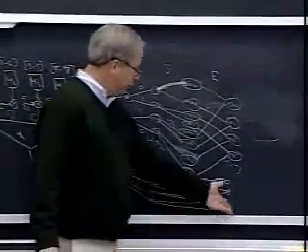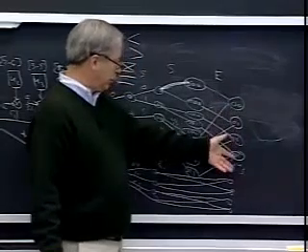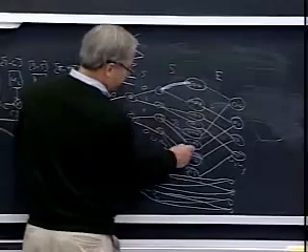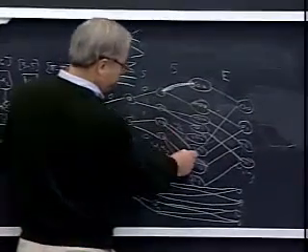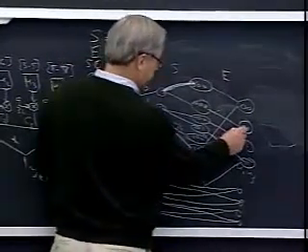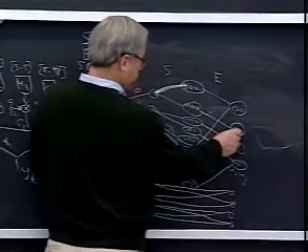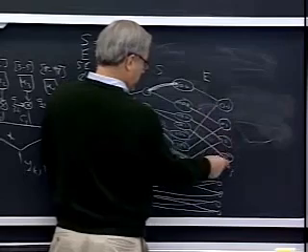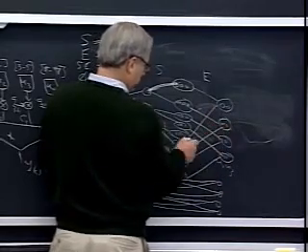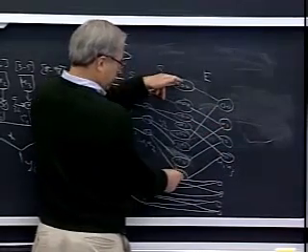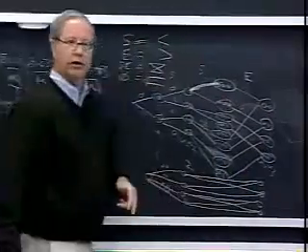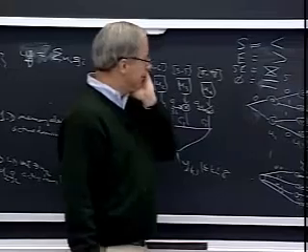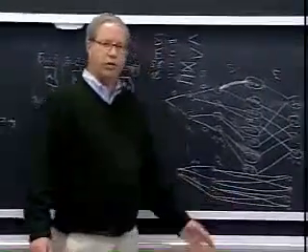And if you think about it, it's really legitimate to think of this. If you think exactly how the Viterbi algorithm works, I mean, really, what's it doing? It's not making any selection here. It's just adding an increment there and then adding another increment, and it's not making any selection till it gets here. So it's perfectly legitimate to think of this as basically being a 4-state algorithm. It really isn't doing any work at this stage. All the work occurs at this stage. All right, if you think about the operation of the Viterbi algorithm, this is a quite legitimate representation.